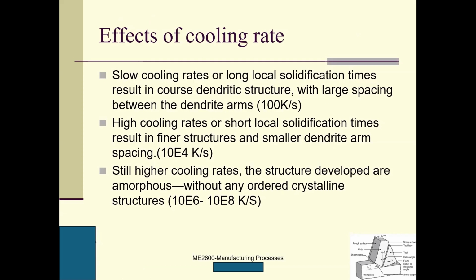And how important is it? A slow cooling rate, or long local solidification time, results in a coarse dendritic structure, with large spacing between the dendrite arms.